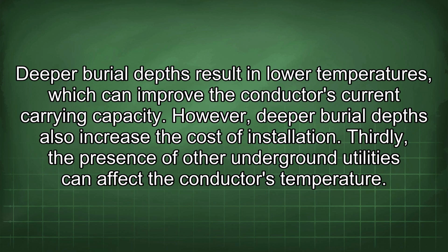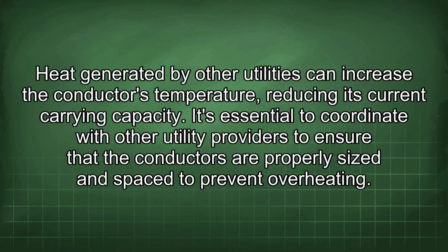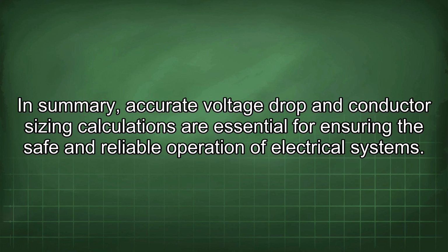Thirdly, the presence of other underground utilities can affect the conductor's temperature. Heat generated by other utilities can increase the conductor's temperature, reducing its current carrying capacity. It's essential to coordinate with other utility providers to ensure that the conductors are properly sized and spaced to prevent overheating.